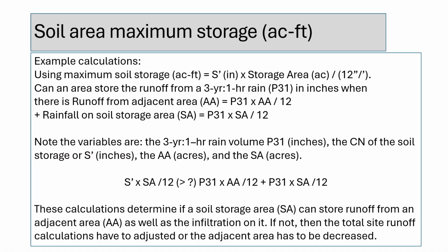If the soil storage area cannot accommodate all of that water, then either the overall site runoff calculations need to be adjusted or the size of the adjacent contributing area needs to be reduced. It is also important to note that there is no storage capacity beneath pervious pavement itself, so all of the storage must come from the soil storage area.